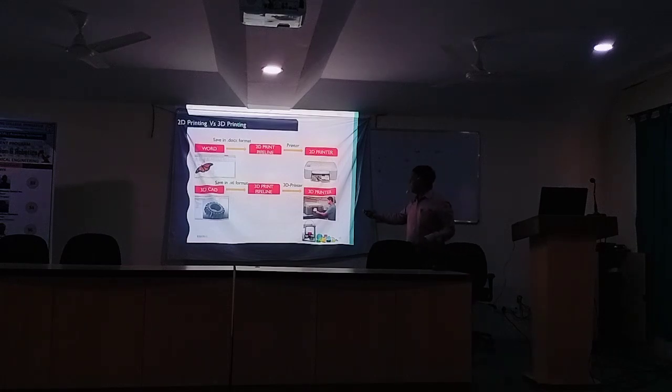Same thing happened here. In 3D printing, first you develop the digital model, that is your CAD model. After slicing, it becomes a number of 2D geometries. Here it is 2D, no? X movement and Y movement. That is, you can say, a 2D printer. Now here, first you convert the 3D into a number of 2Ds.